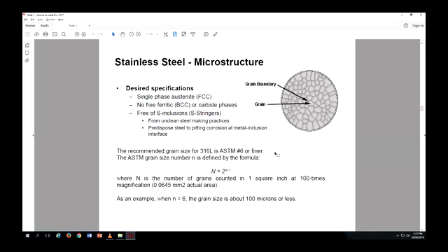When you fabricate the material, either by cold working or other techniques, you start with molten metal, right? And the way it solidifies into these crystals, into the solid structure, is very important to give you a uniform small grain structure. Otherwise it's going to give you large diameter grains, which is much weaker again, and you will have a lot of stress concentration and so on.